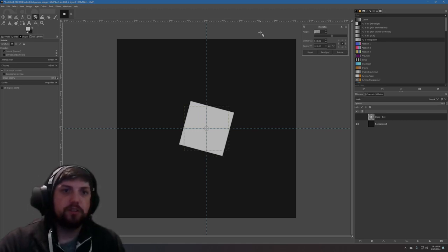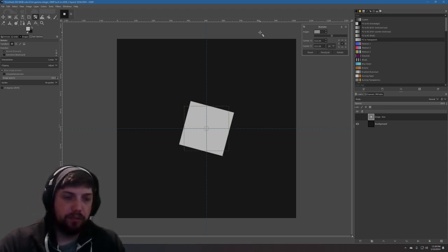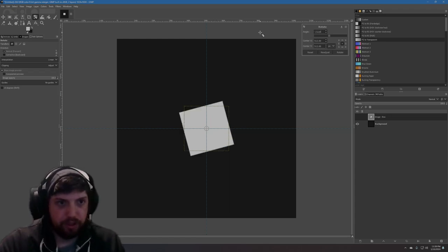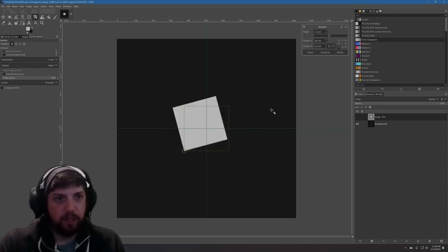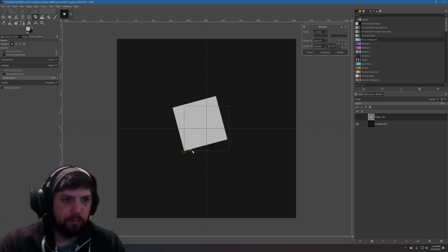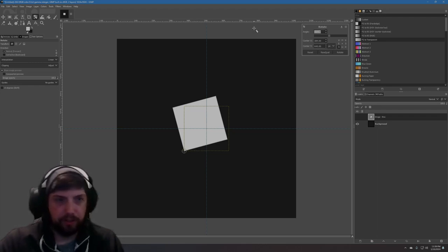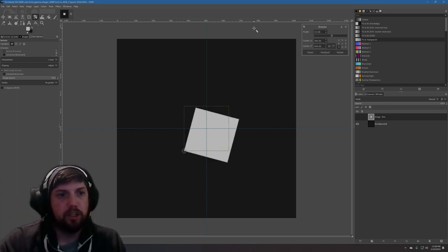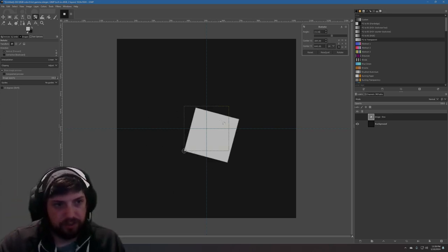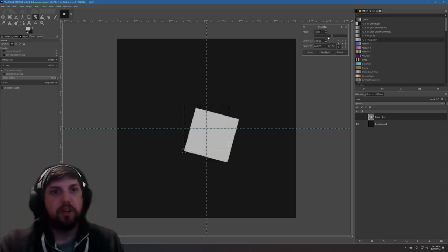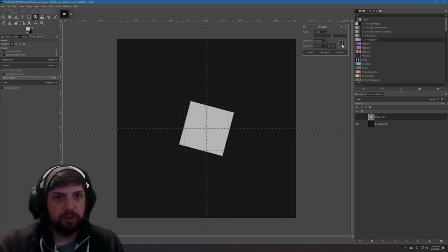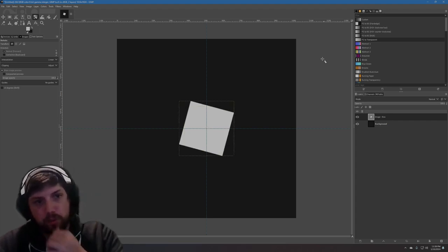The angle allows for negative directions, so right now we have 15 degrees. We could do a counterclockwise rotation with negative 15. If we move this pivot off to the bottom left, we can see this a little bit more. If we do negative 15, it's rotating this way. If we do 15, it goes downwards, so this is clockwise. Previously it was counterclockwise. But we're going to start off by simply doing a rotation about the center. So clicking Rotate is going to apply this rotation.